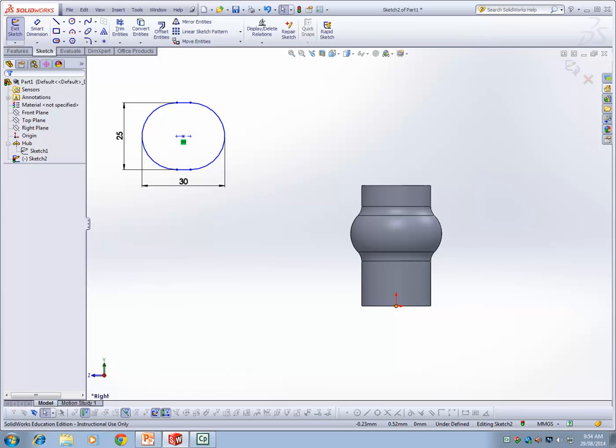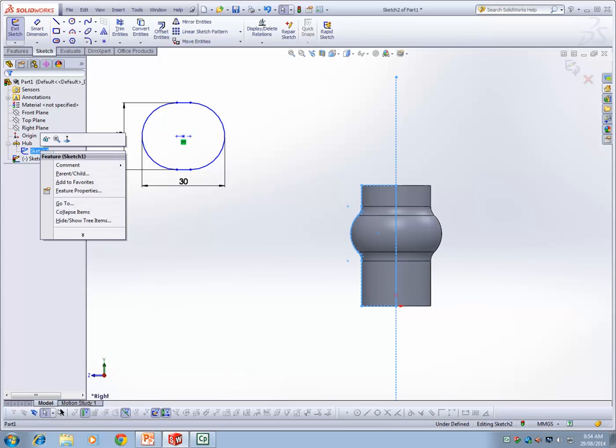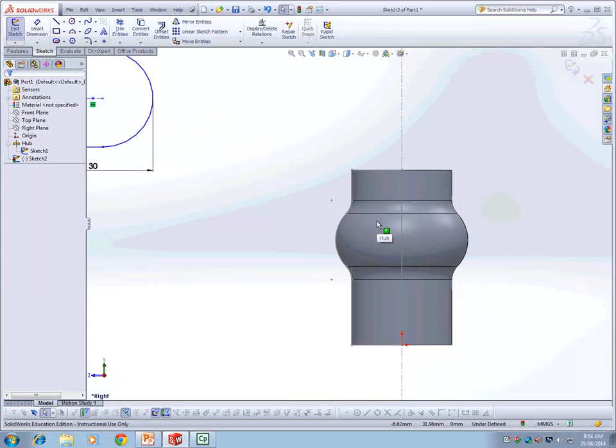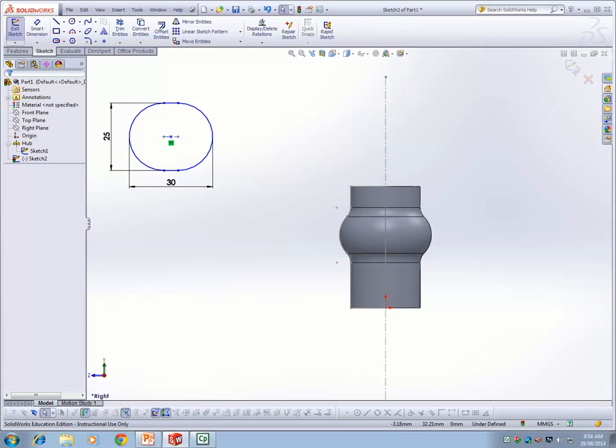So in this case, first you add a sketch. You will be using the sketches already drawn in the new sketch. So you need to make them active so they become blue. Okay, so you want the distance from the center point here.